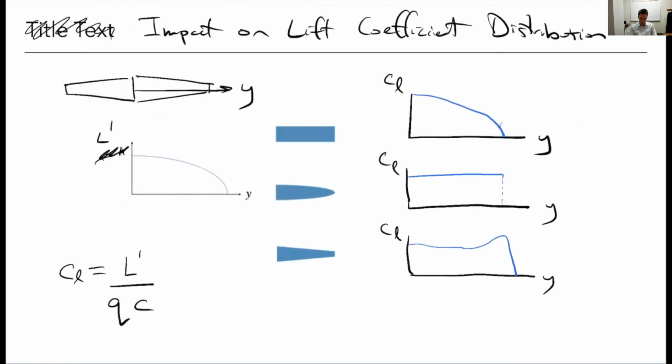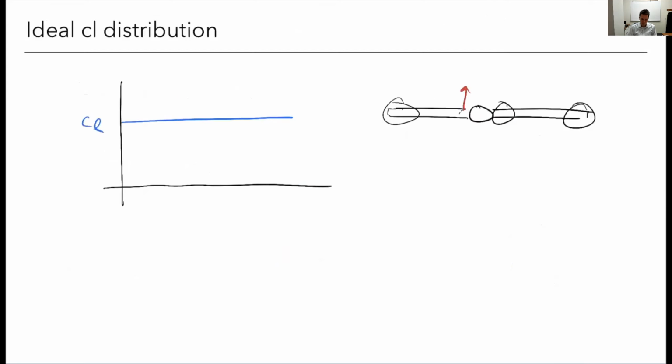This is actually why this type of lift distribution here would be particularly undesirable. Notice that it's going to want to stall right here, or else I'd have to really cripple my airfoils on the interior to get them to perform worse. So this is a particularly bad shape for me. So an ideal lift distribution actually may not be quite straight. We generally would probably prefer that it was pretty constant, and then towards the root it probably dropped a bit. Alternatively, we could use airfoils towards the tip with a higher CL max, but for your airplanes, you're probably not going to use different airfoils.